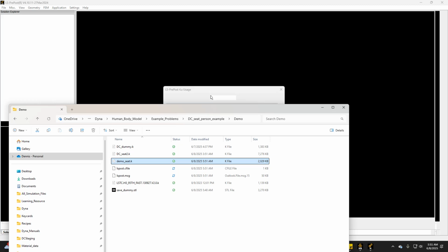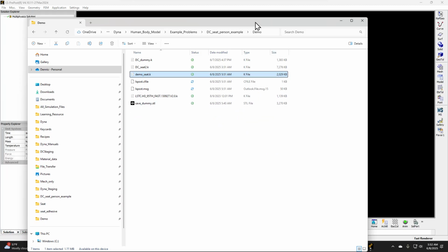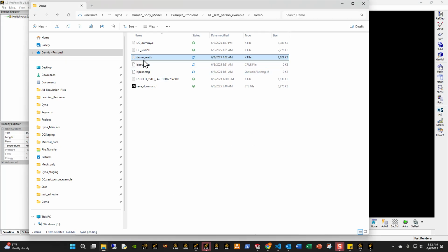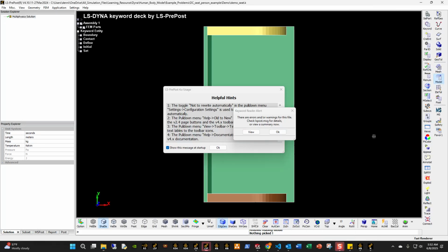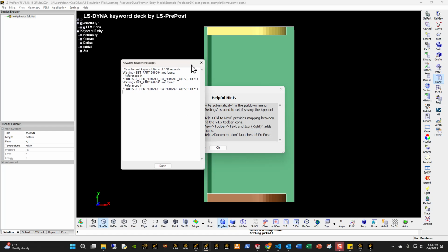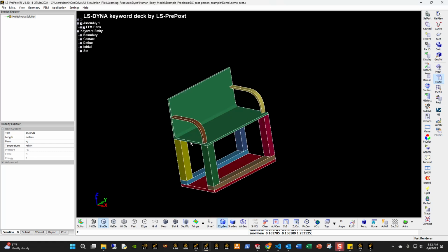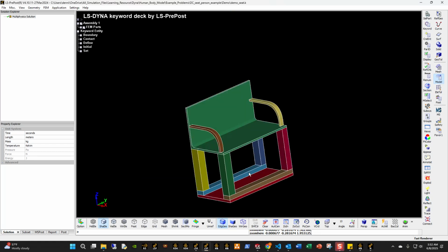The way we fix this is, first thing, I'm not going to do the include file yet. Just for the sake of consistency, I'm going to comment this out and save it, so this include file does not exist anymore. And then I'm going to drop the demo C into LS-PrePost. Okay, this is fine. I have a tied contact surface I didn't talk about, which is down here. I'll explain what this is in a bit. I already had it ready because that was part of my template from the earlier trial runs.